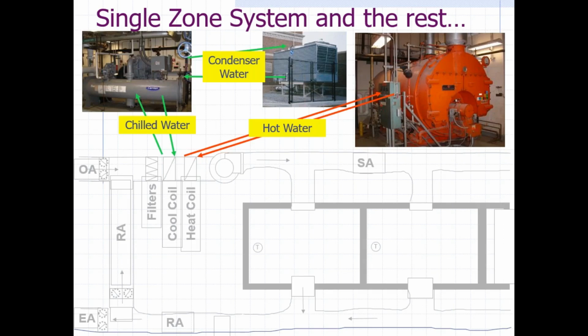So, I have this thing I call a cooling coil. Well, what a cooling coil is, and I think you know this, is the chiller makes chilled water. So it might make chilled water that's maybe 42 degrees or 40 degrees or 45, who knows. And it goes through these chilled water lines into the cooling coil in the air handler, and it goes back to the chiller. So then the air would pass through the cooling coil and cool down.